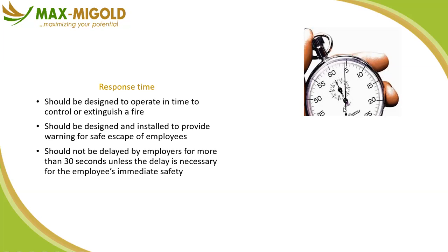So one method you can use again is to have multiple muster points. There is no law that says your muster point must be at the gate. In fact, in some cases, the entrance gate may even be the most hazardous area. So if you are into logistics and vehicles drive in and out of that gate, be sure that if a vehicle should fail brake, it might just collide, it can actually run into the muster point. So the muster point is the safest point at the moment within the facility, which you then need to determine using the hazard identification metrics.